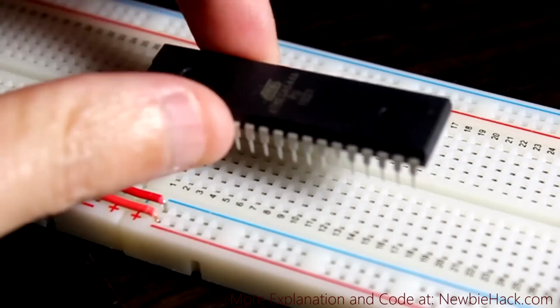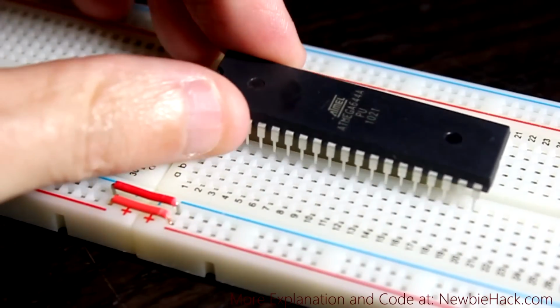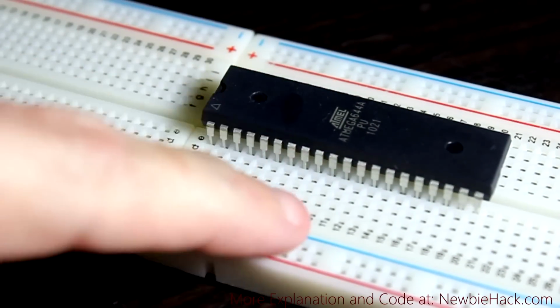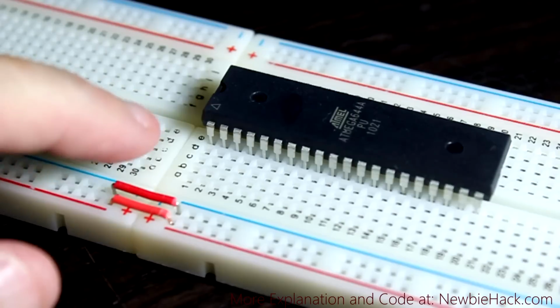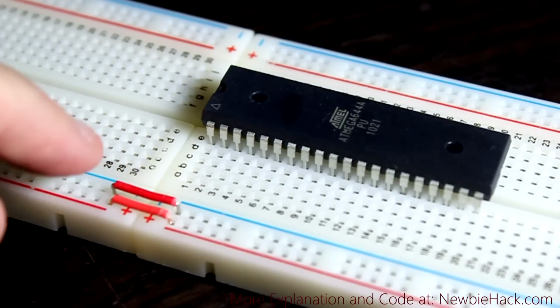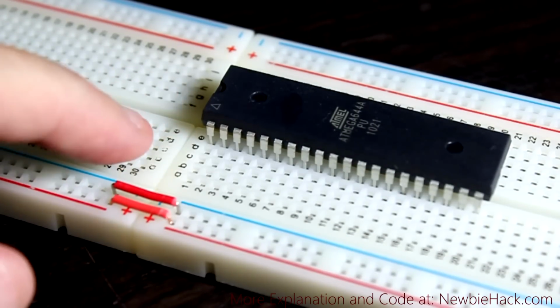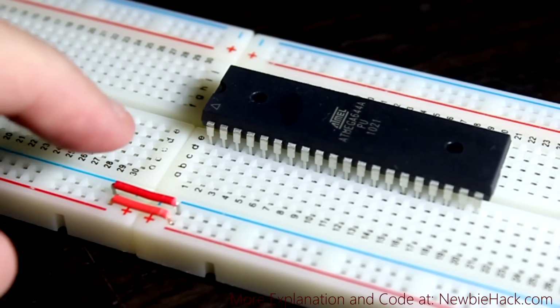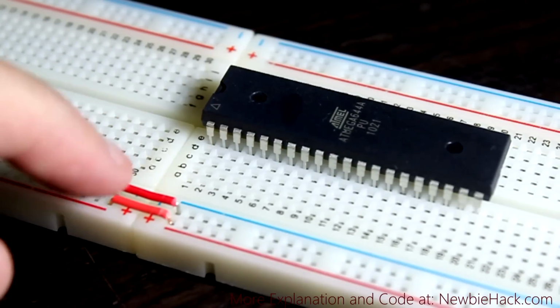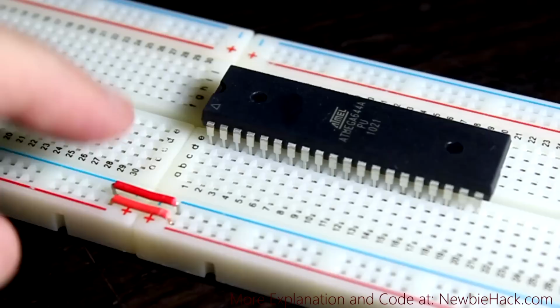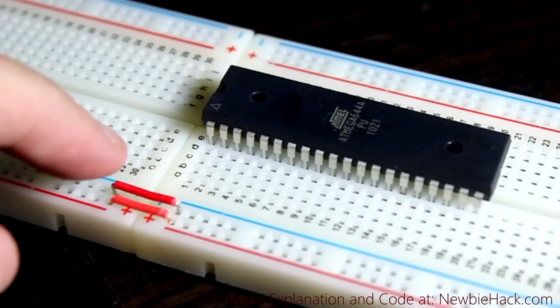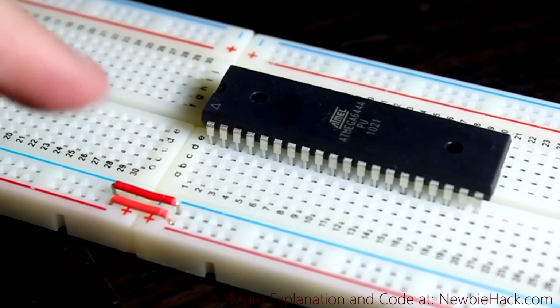Let's put together a circuit. We won't be putting the crystal on in the beginning because I want to make sure the microcontroller is working, and we're going to program it with a blinking LED so we can look at the timing of the LED, the way it's blinking. We'll do it blinking 1 second. It'll be on 1 second, off 1 second. And then when we change the fuses, we'll rerun it and see how the LED blinks. It should be blinking a lot faster, like 18 times faster.